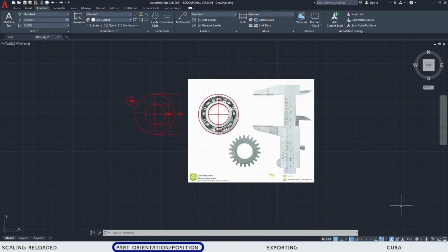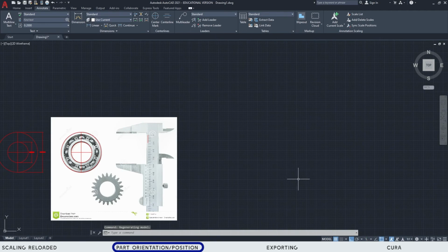Now, why is orientation important? The mechanics of 3D printing necessarily means that the layers of an object are parallel with the print bed. That understanding will assist you in deciding the orientation of the object that you're going to print. So what I want to do is create an object and look at it from different orientations on the print bed. So let's create a cube here.